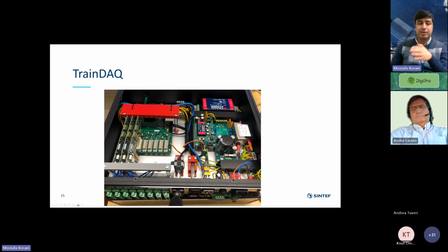programmable, so we can select between accelerometers, velocity sensors, temperature sensors, or even microphones, ultrasound microphones. And we have high-speed ADCs plus FPGAs there. So all the machine learning algorithms and edge computing will be deployed on the FPGA, so we can save power and also run it quite fast, because some of these algorithms are so complicated that we would need a high performance PC to do that. But in an FPGA, we deploy them on hardware.